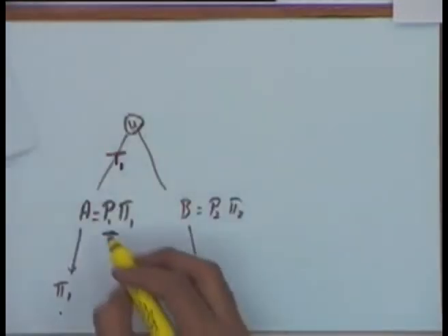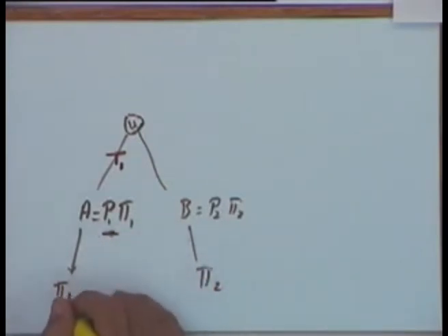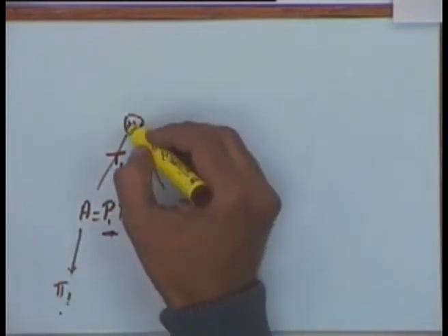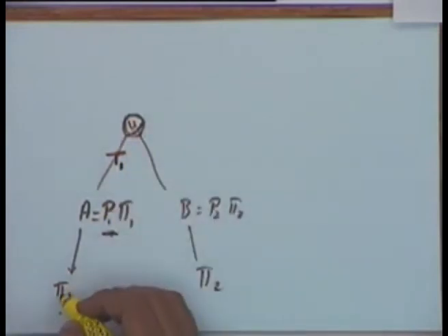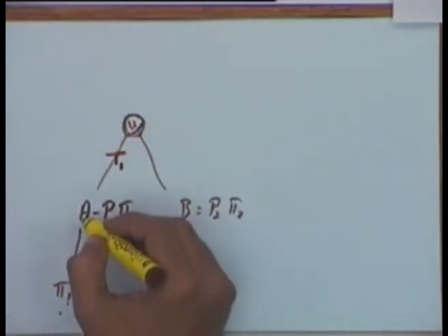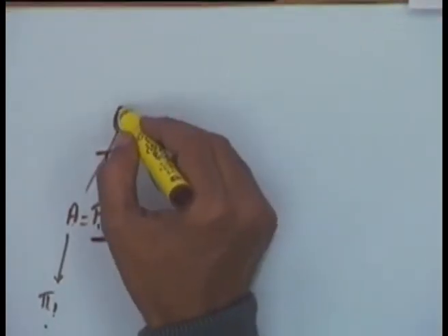And as I mentioned, the process of instantiation does not alter the boundary model for these primitives. It does not alter the topology, and the BREP model will remain unchanged. So when I am evaluating this union, the BREP model for pi 1 will be the same as that for A, and will be the same after transformation T1. So the expensive process will still be the union.